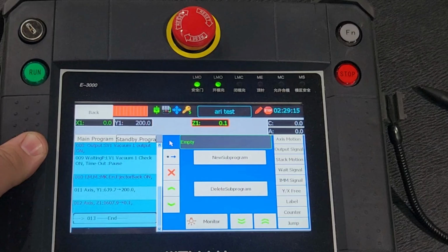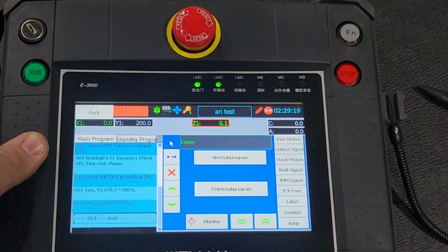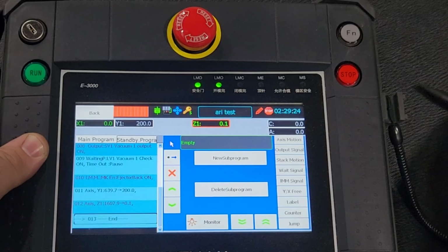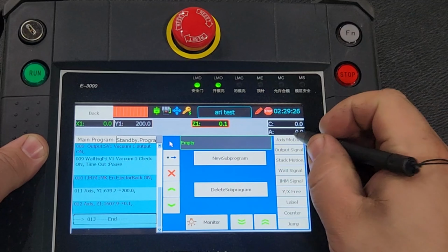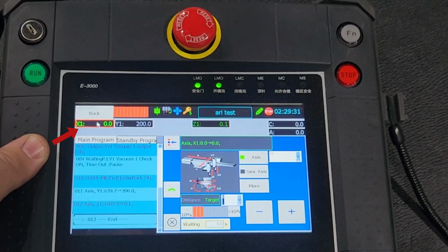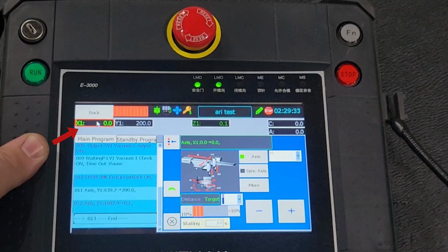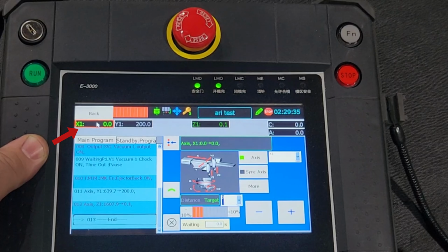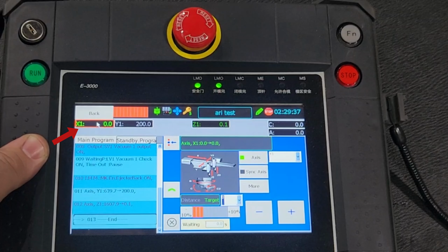Now that the robot is in its home position, the robot will go ahead and give the molding machine a mold close signal so that it can close and start making its next part. While that's doing that, we'll go ahead and move our X axis out to the part drop area. You'll see the X is currently highlighted green. As it moves out of its home flag, it will move to white. Once it's over the part drop flag, it'll turn brown. Only when the X is green or brown is the Z okay to drop.